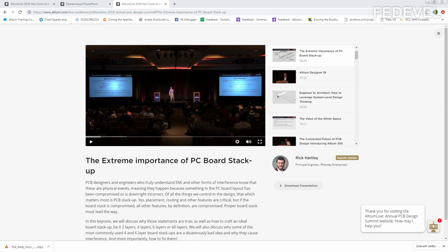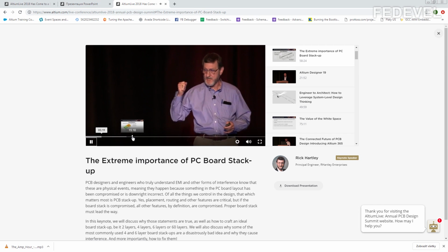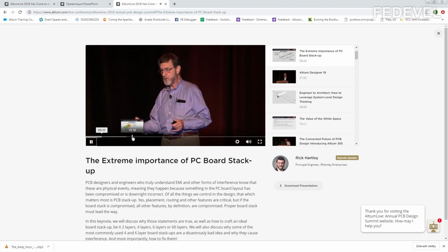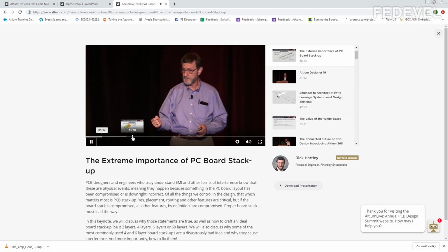Now, a little bit more from the presentation. Just for those of you who give a rat's behind. One thing I want to really point out and make clear to everybody, it has absolutely nothing to do with clock frequency. The frequency of a circuit is associated with the rise and fall time. Every single thing that ever goes wrong in a circuit, period, no exception ever in a digital circuit, happens during the rise and fall time.